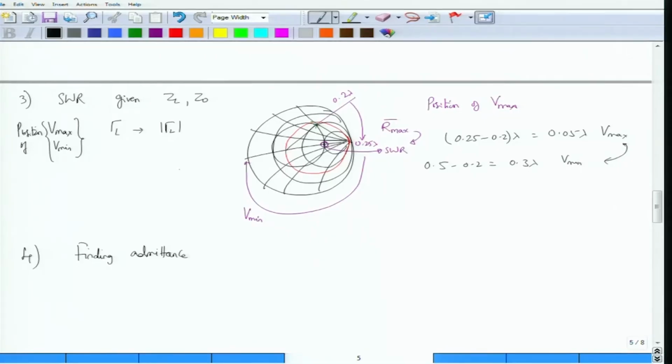You recognize that the reflection coefficient gamma at any point on the transmission line, let us say gamma of z, is nothing but the normalized impedance seen at that point, call this z bar of z, minus 1 divided by z bar of z plus 1. I know this is slightly confusing, but please bear with me. Now what is the corresponding expression in terms of admittance? z bar z is nothing but 1 by y bar z, so this is 1 by y bar z minus 1 divided by 1 by y bar z plus 1.